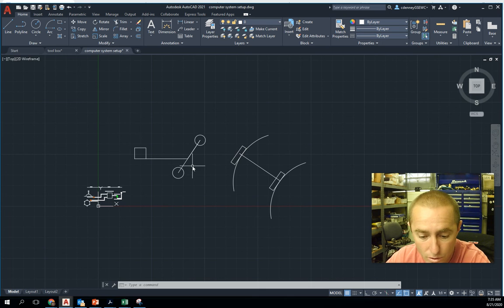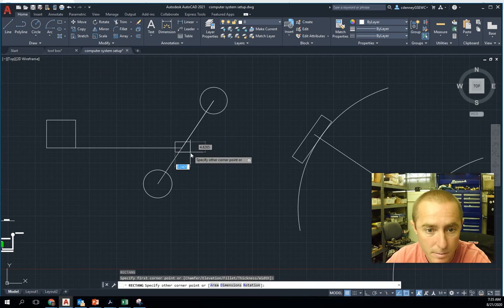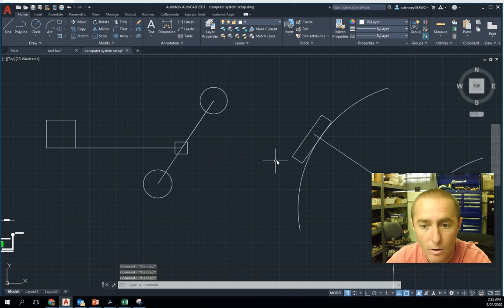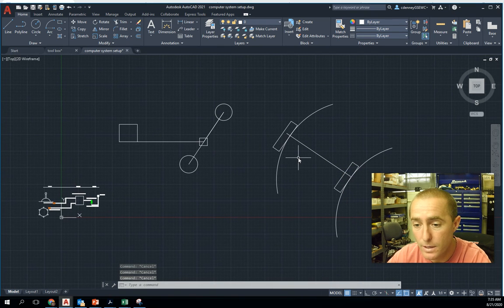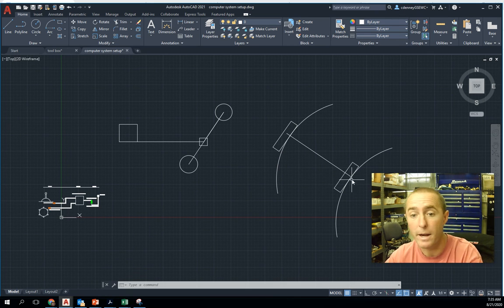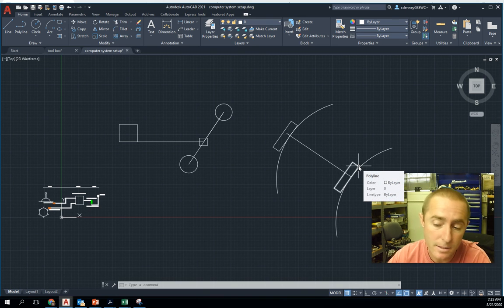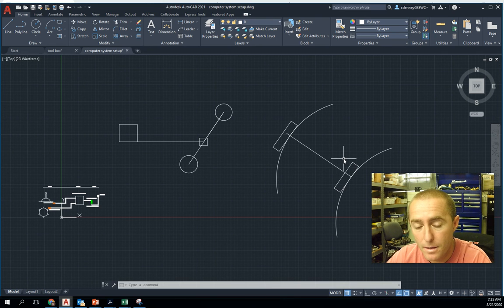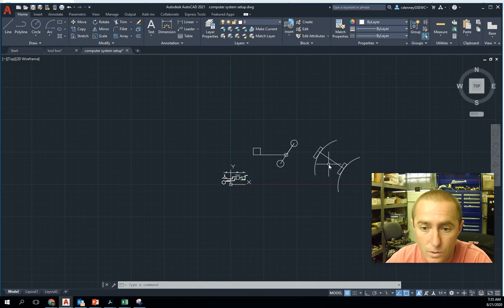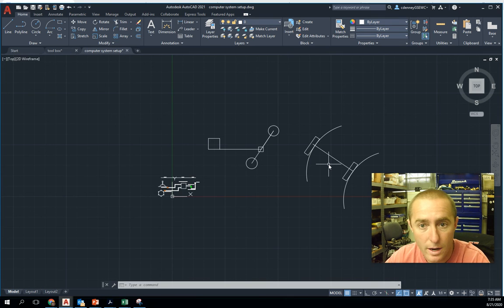And our rear differential, which would be right around here, actually has some unique gearing that we'll get into later that allows this wheel to spin faster than this wheel. And the opposite, if we were making a left turn, it would allow my outside wheel, my right wheel, to spin faster than my inside wheel, my left wheel. So that's the drivetrain, and that differential is a very important part of that. You have your drive shaft and your differential working together to make those two things happen.